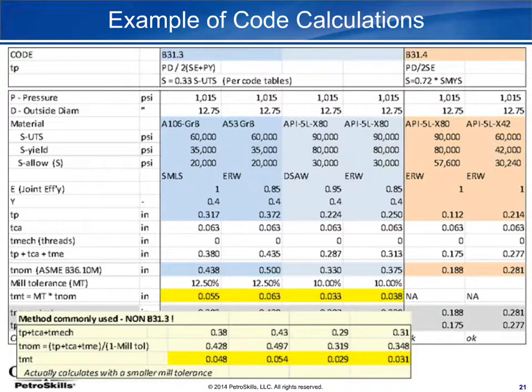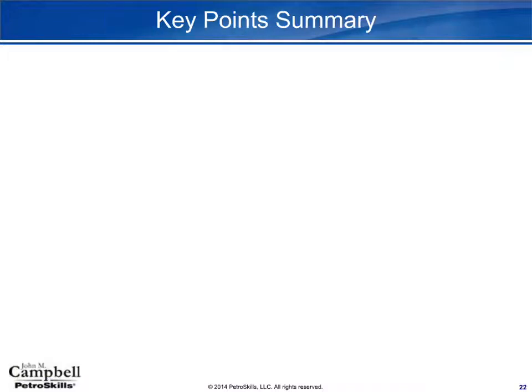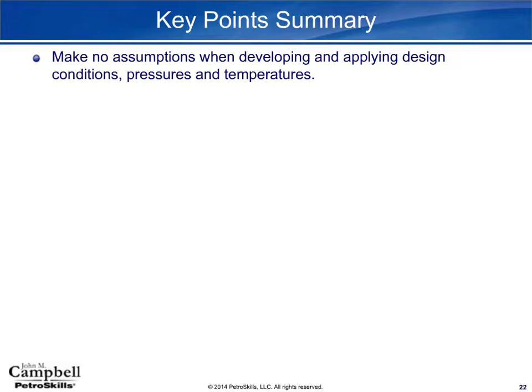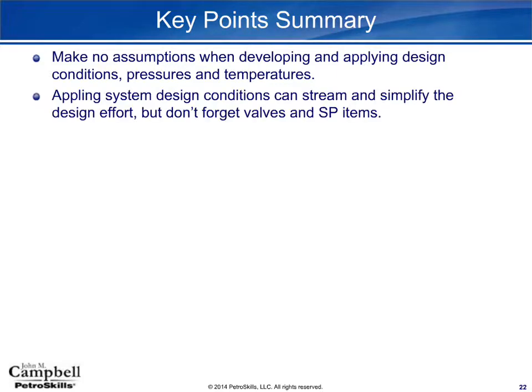First of all, of course, when we're talking about design pressures and temperatures, make no assumptions. Make sure that we understand where they're coming from and what they apply to. Realize that those design conditions are going to apply not just to vessels and piping and flange ratings, but also, don't forget, your smaller items. Specialty piping items are always an issue.